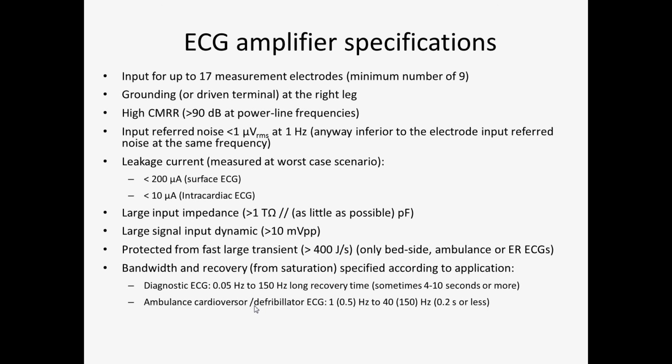So I told you that every time you put a patient or a participant in contact with an amplifier, you put them at risk. The reason is leakage currents. We don't realize it, but the simple fact that we have something connected to the mains, like a computer, will create some accumulation of charges and leakage of current from the power source onto the chassis of the device.